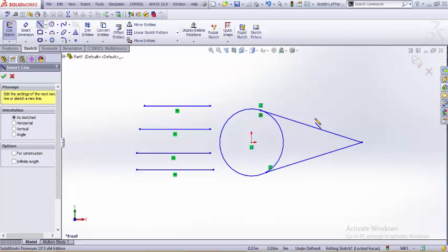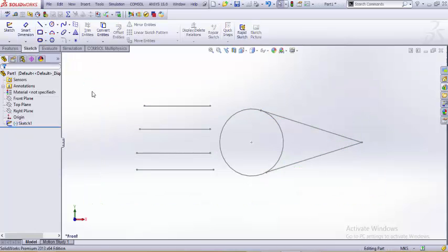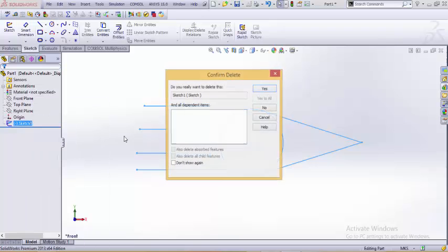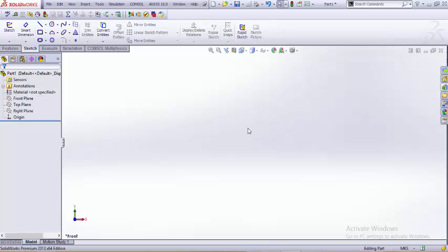even though this process sometimes increases the skin drag or friction drag due to the fluid viscosity, but that would depend upon the length of the streamlined object. That means this extra bit of portion that you need to add to this blunt object reduces the pressure drag. We will be discussing aerofoils in detail in some other videos, but for now we just limit our discussion to what's needed for this design. For that we remove this part.